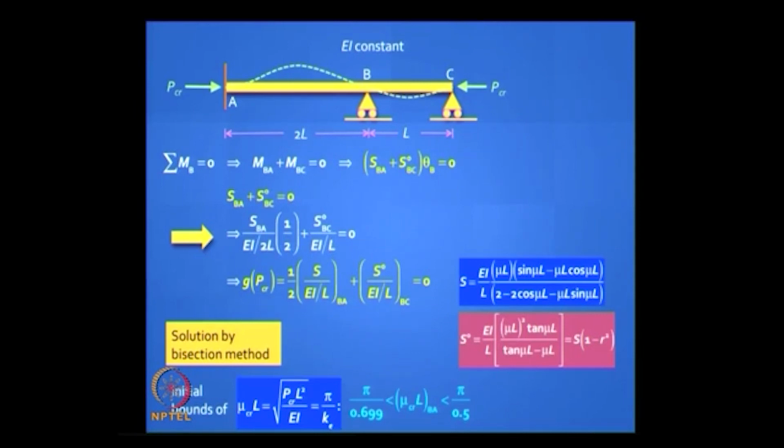It is L E squared for any set of boundary conditions. So it is very convenient. You identified 0.699 and 0.5 for element BA, and for element BC can we still use BA? Yes, we can, because the two spans are related. For the second element it is half the value as that of the first element, right? Does this make sense? It is all very logical.